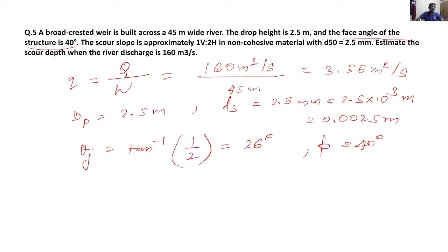Now it's a very straightforward question, by the way. Since we are moving into advanced sediment hydraulics in this course, we need to understand, or memorize, a few empirical expressions also. That is how this course is being designed. So hc, that is the critical depth, is (q square by g) power 1 by 3.